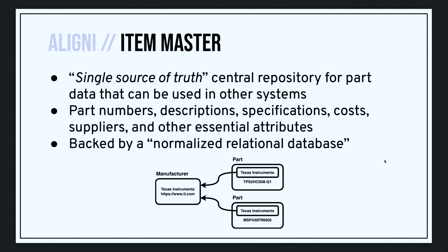Single source of truth. It's a central repository that you can use not only in this system, but also in other systems. And it's backed by a relational database. So you get nice, real rich relationships between the data and the tool. So if a part is referencing a manufacturer and that manufacturer name changes or the website changes over time, you'll have links that will be updated within the tool, and you're never going to have stale copies of data lying around in your parts.